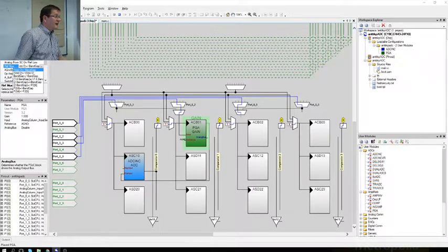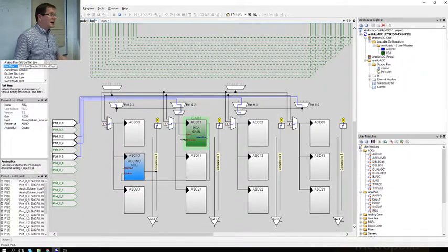But for 5 volt operations, actually 1.6 times band gap plus minus 1.6 times band gap would give you roughly a value that is quite nicely translated into volts.